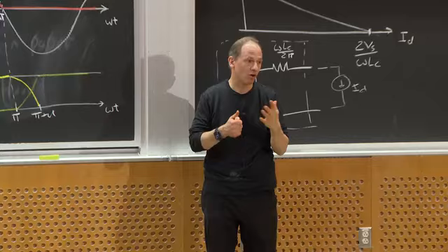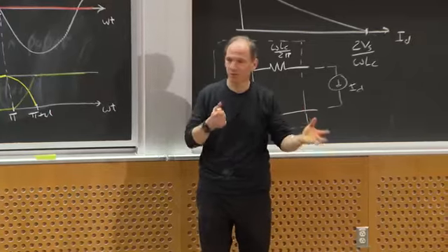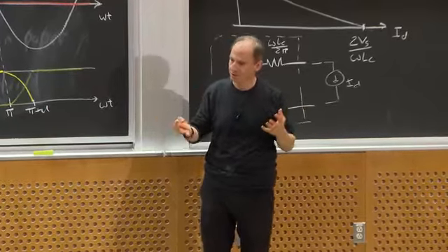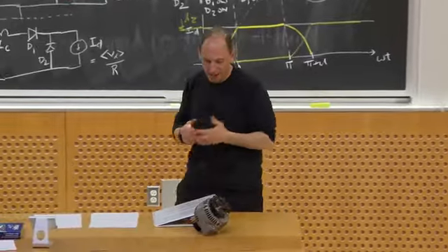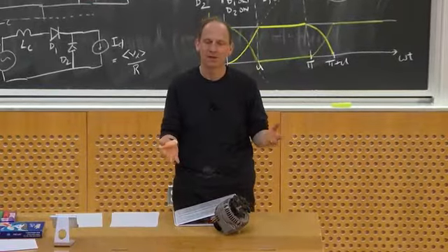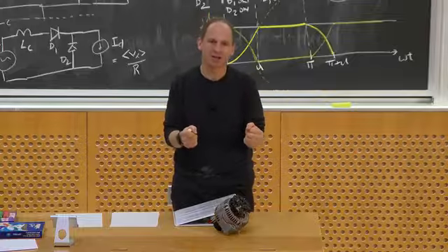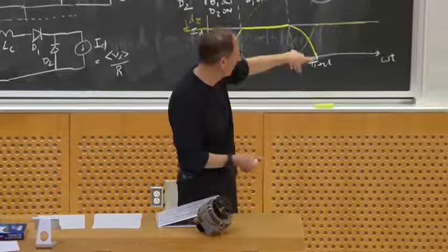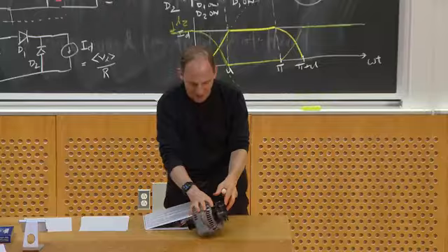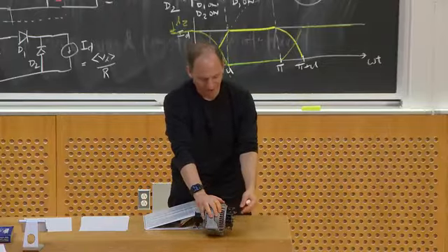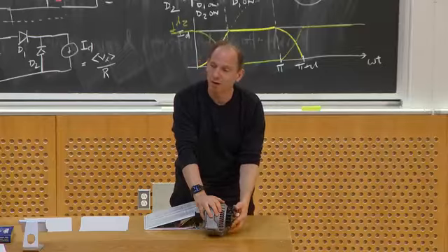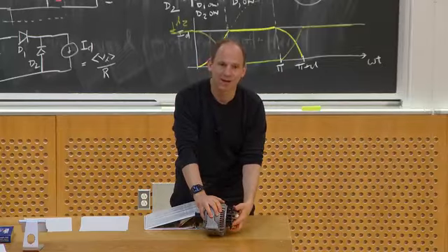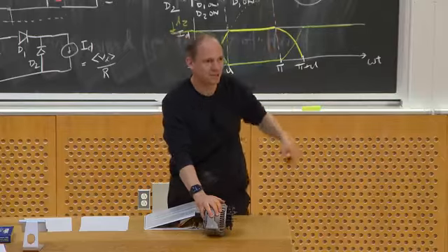And so it actually almost looks closer to a current source, or somewhere between a voltage source and a current source. And in fact, that can cause trouble in an automotive application because there's something called a load dump. Imagine you're charging your battery with lots and lots of current. So what they do is they crank up that voltage Vs. That voltage Vs is controlled by an electromagnet, which is then regulated to get the right voltage to give you the charging you want. But if your load suddenly goes away, that's way too much voltage, and you get this big spike in DC voltage.